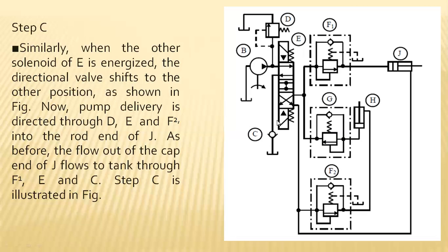So at this oil reservoir, there is a small mistake that has been made: that check valve will be opposing in nature, because this check valve has to be in reverse condition, because free flow has to take place for draining into the oil reservoir. There is a mistake in the diagram. So here this is the free flow, this is the obstruction flow, and this is the free flow. Here instead of inverting, it has been specified like this. So inverting, this is the diagram, and this one. So the already entered fluid will be drained back to the oil reservoir.